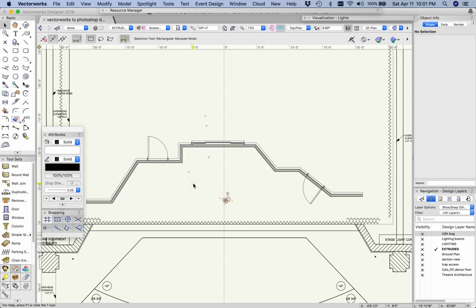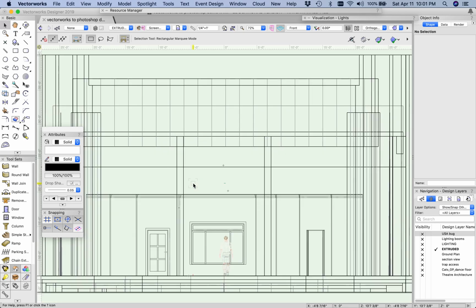So from this point, I've done all of my modeling on the wall. I've added this trim. There's trim and molding around the windows. If you were going to do any kind of panel molding, you can either do that in the model or you can do it later on two-dimensionally in an elevation and use that. So I think for right now, I'm just going to leave it like this. And I'm going to choose this wall with the door in it for my paint elevation.